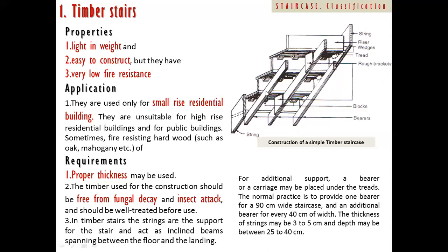You can see the strings running at the edges, so that the tread and riser can be housed inside the string, and that is how the fixing is handled.